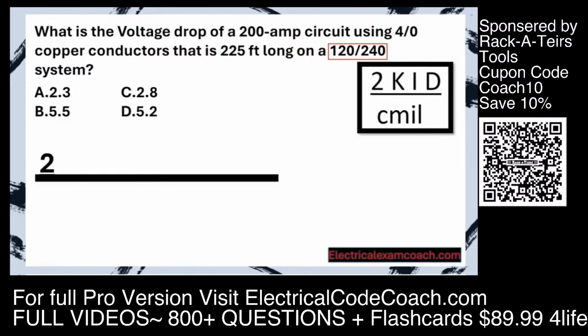Then I like to go ahead and input my X down for multiplication so I don't get my numbers mixed up. Then let's go to the K, and that's going to be dependent on the type of conductor. In this case, it's copper. So the K factor for copper is 12.9. Now we need to look at I, which is current. We put down our X for our multiplier. We go to our question, and it's a 200 amp circuit. So we're going to put 200 down.